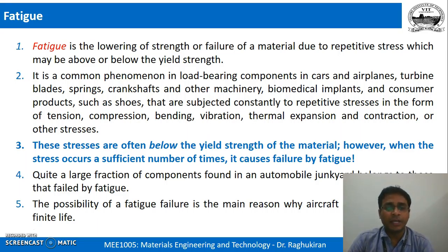Very similar thing is what happens with materials also, which have no life, but still they undergo fatigue and exhibit fatigue failures. That means you are not applying the load to the extent of yield strength or to the extent of tensile strength and so on. You may be applying lesser load, but even then the material fails.